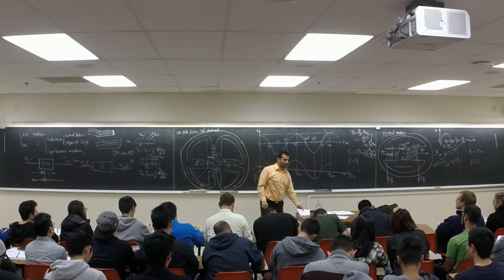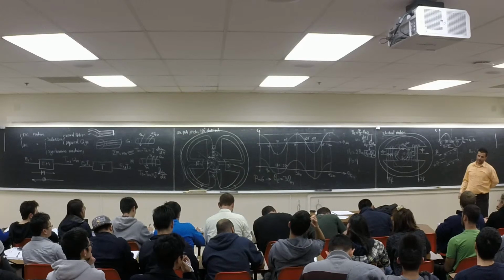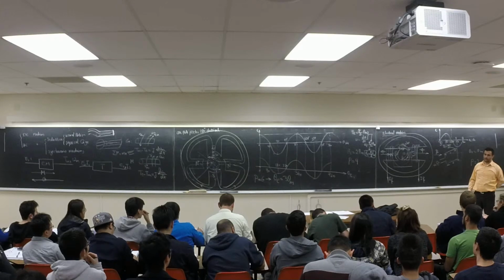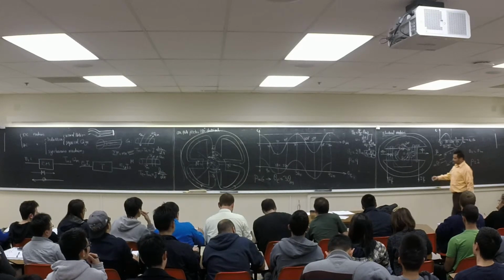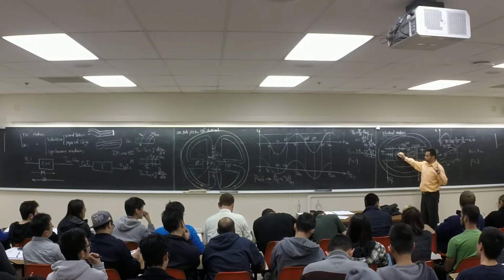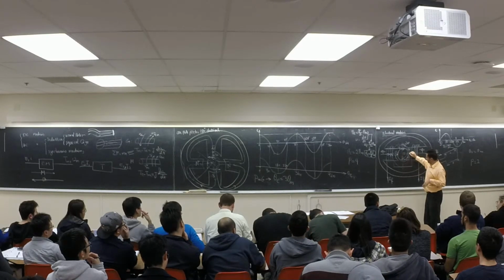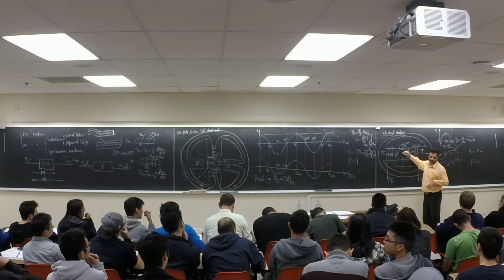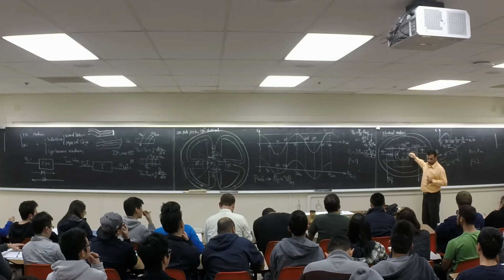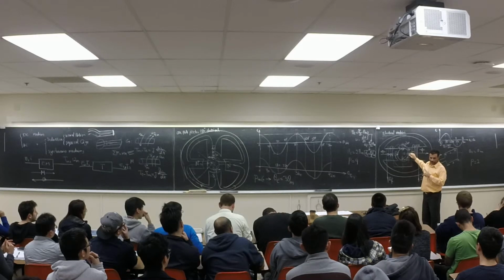So now, can you tell me how much is the pole pitch here? 2. Can you tell me what's the pole pitch here? 2. Oh, 2 degrees cannot be. We want to say it another way. You should start from N and go to the next S. They call this one pole pitch. How much is the one pole pitch here? 180 degrees electrical. Everybody is 180 degrees electrical, but 180 degrees mechanical as well, right?